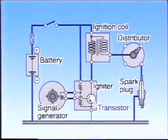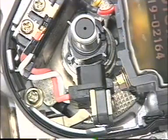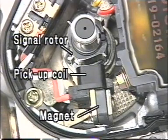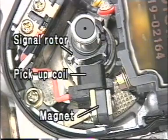In the transistorized ignition system, the ignition signal from the signal generator is transmitted to the transistor in the igniter. This transistor turns the primary current in the ignition coil on and off. The signal generator has three components: a signal rotor, which makes one turn for 2 revolutions of the crankshaft, a pickup coil, and a permanent magnet.